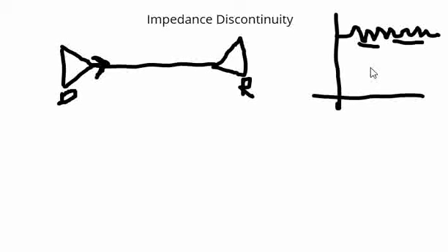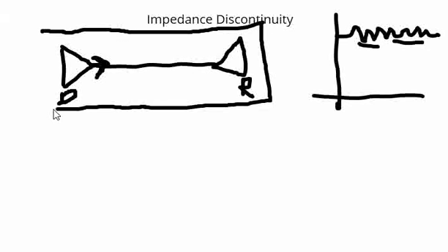Now, what are the common causes of impedance discontinuity? Let us assume this is a PCB on which we have a driver and a receiver, and there will be other components as well, right? And if a signal is input and there is a via on this particular signal in the PCB, and the signal is routed in the inner layer and then connected this way, this via actually introduces impedance variation. A via can be modeled basically with an inductance and capacitance, which are the elements which cause impedance variation.